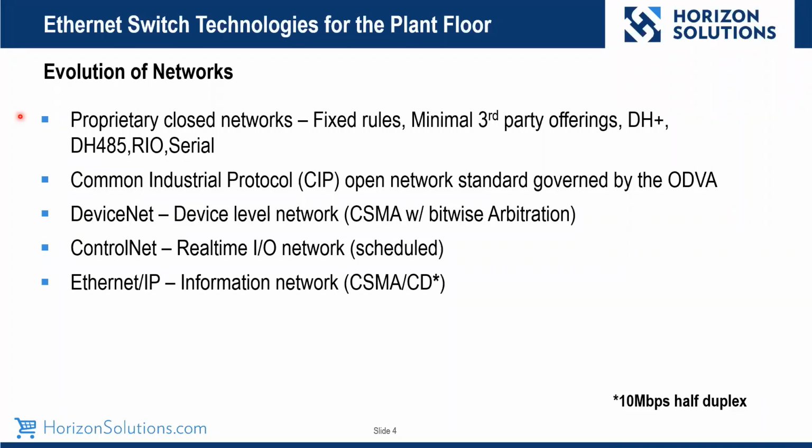And when this first came out, EtherNet/IP was 10 meg half duplex. So it was not really considered an I/O network at the time. So times have changed quite a bit. So now we're doing things in sub-millisecond on EtherNet/IP due to switching technology and full duplex.